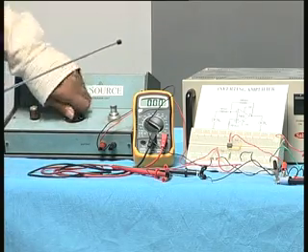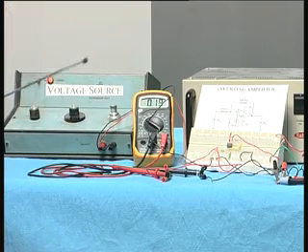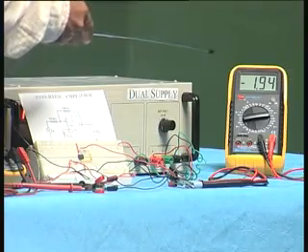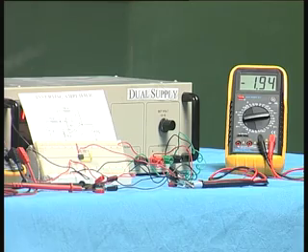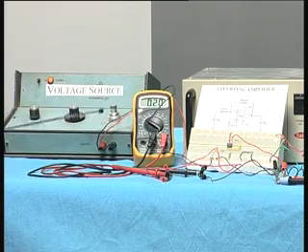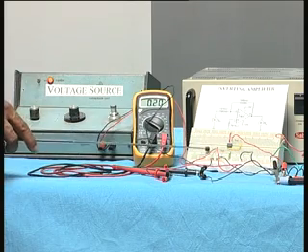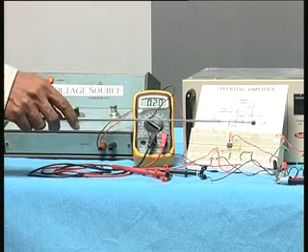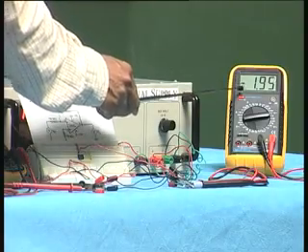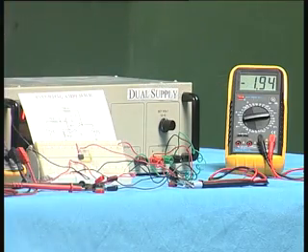So you can also see another very important thing. For example, I am again giving 200 millivolt, 0.2 volts, and the output is 2 volts, nearly 1.94. But what is more important is I am applying the red to the input, the black to the ground. That means I am applying positive 200 millivolts, and multiplying by 10 I should get minus 2 volts, and you can see there is a minus sign here. This is actually minus 1.95 volts.